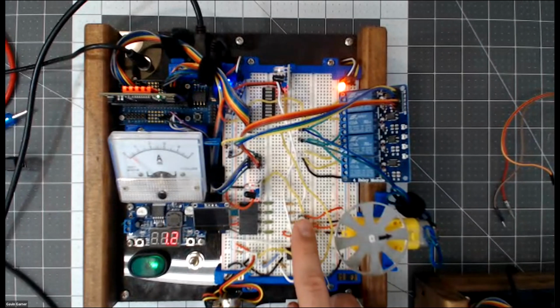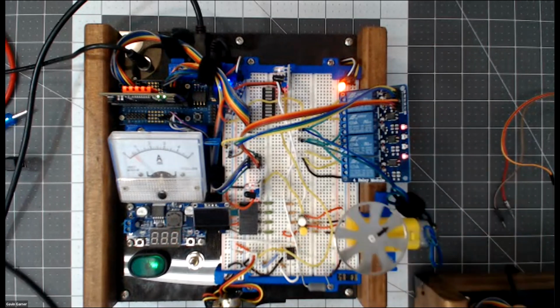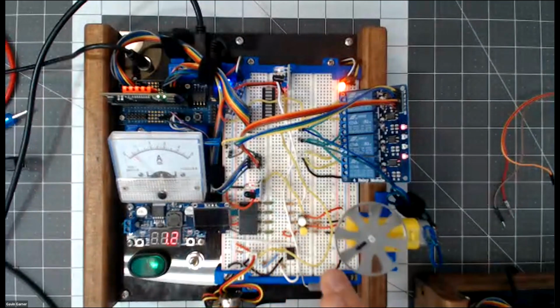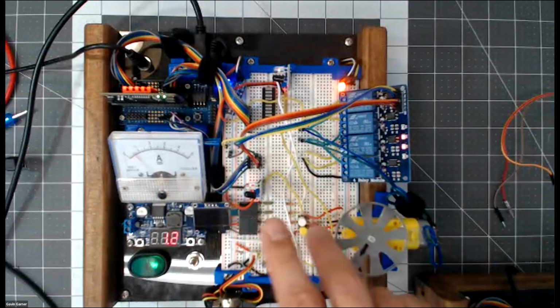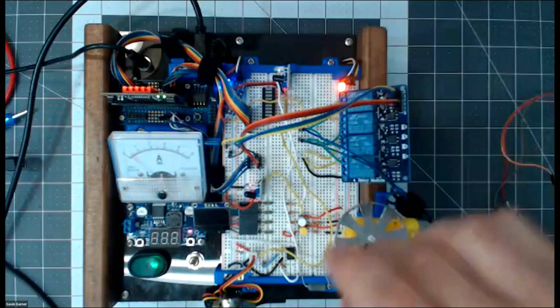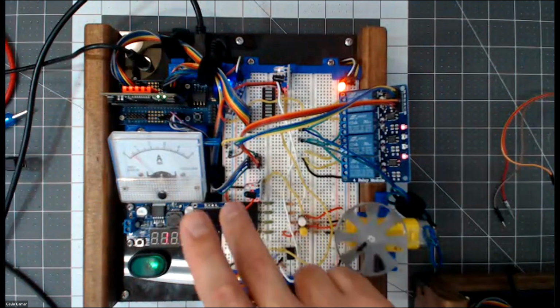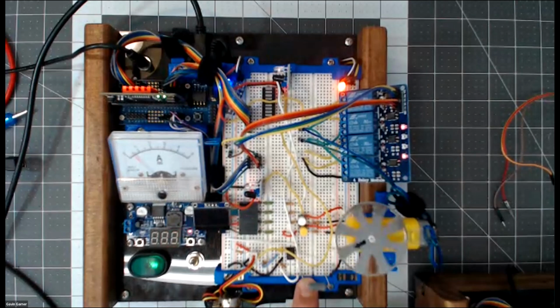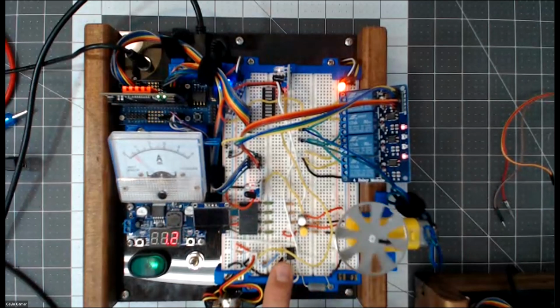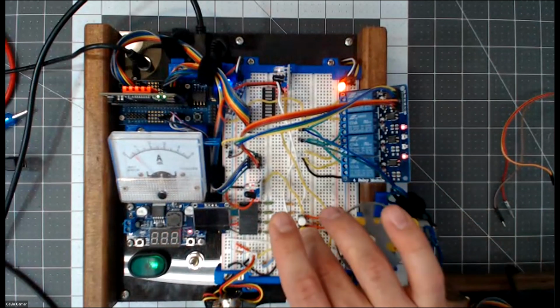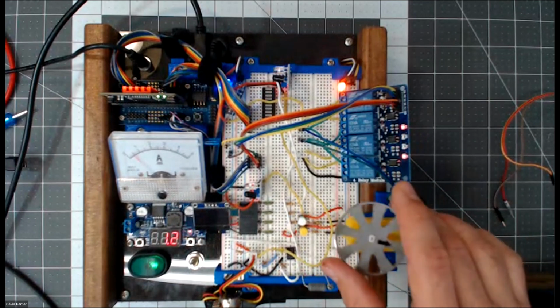And so they basically would have a window up and down button. They'd hit the up button, for example, and it would start to spin, winding up the window until it hit the limit switch. They'd hit down and it would go until it hits the limit switch. And if it's going up and it detects too much torque, we've got a little bit of a voltage on this shunt resistor going to the comparator, and it gets cleaned up by a little low pass filter. It automatically stops and reverses to go down.